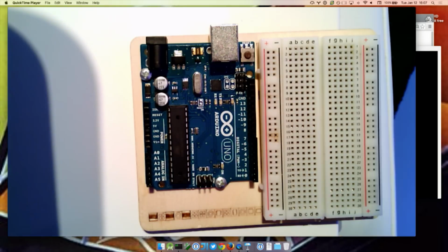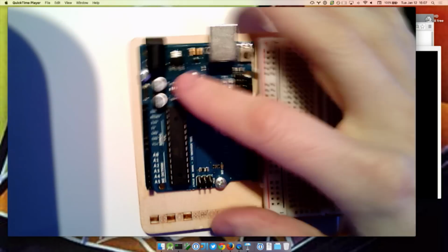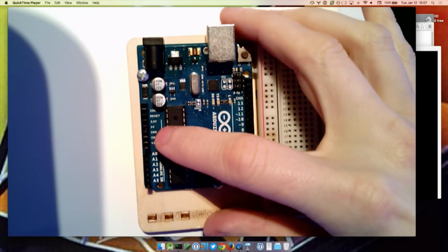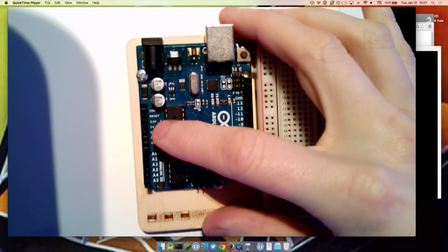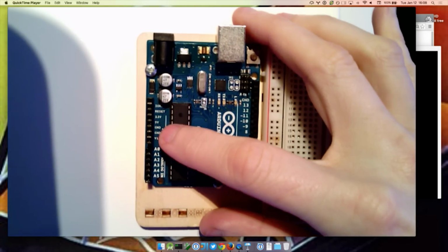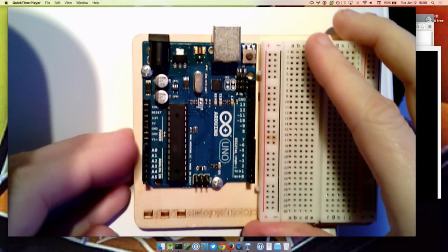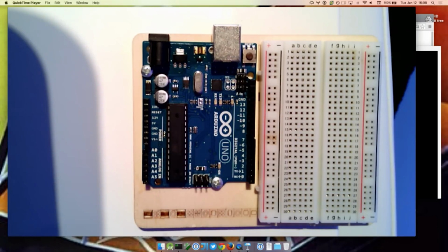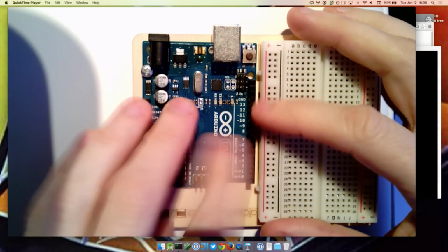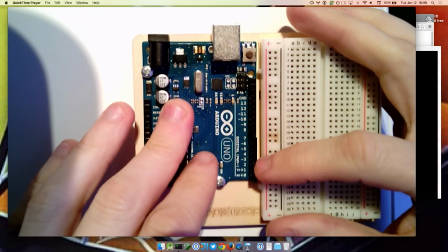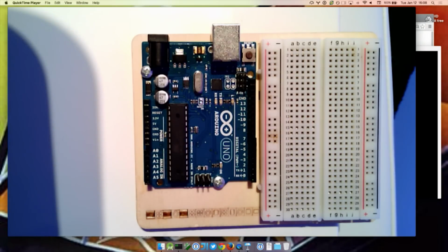And it has a few different kinds of pins that I'm going to point out now. There are these special pins, one that says 5V, which is your reference 1, and a ground, which is your reference 0. It has some analog inputs that we'll use to read from analog sensors, which will come up soon. And then it has a whole bunch of digital input-output pins. Some of them have a tilde in front of them, which just means that they can be enabled for PWM output. And that's great. So the Arduino is wonderful.